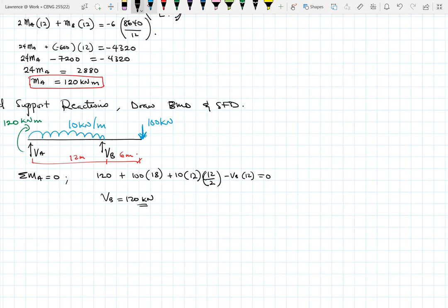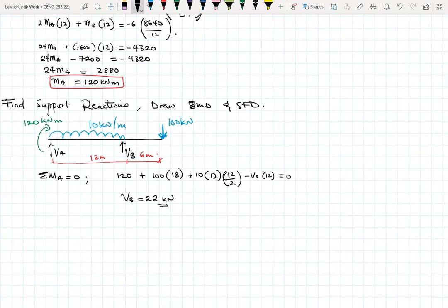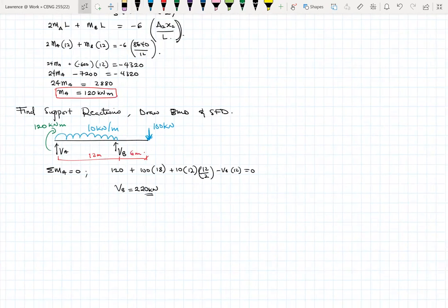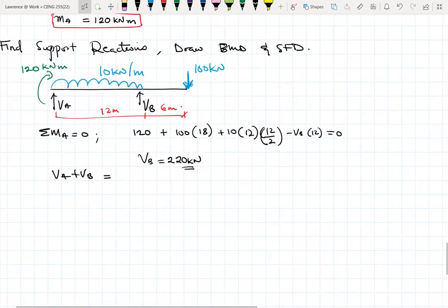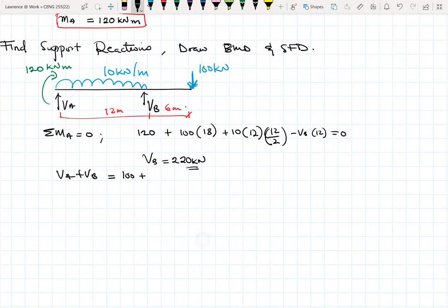It's supposed to be 120. Okay, let me see. 10 times 12. Okay, yeah, it's 220. All right, it makes sense now. Thank you for the corrections. Okay, great. So 220 kilonewtons. Now let's find VA. VA plus VB will be equal to 100 plus 10 times 12, right? So this will give us 220, which means that VA is 0, right? So the reaction at A is 0.